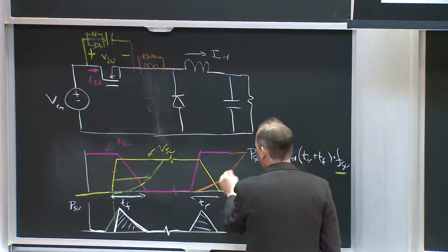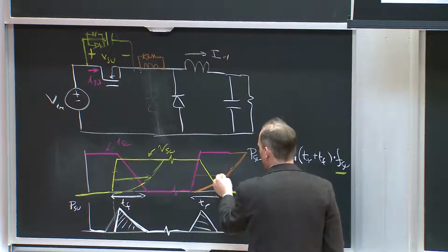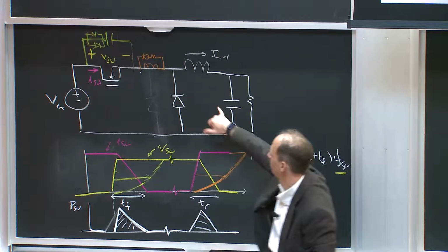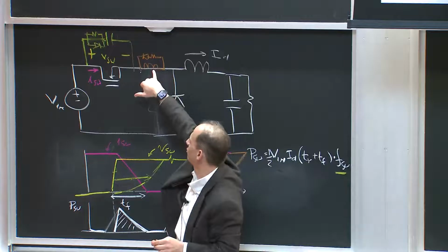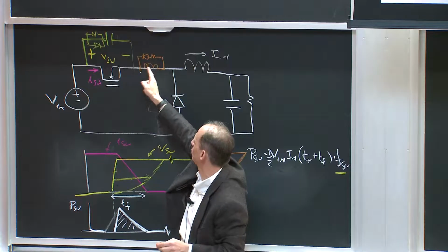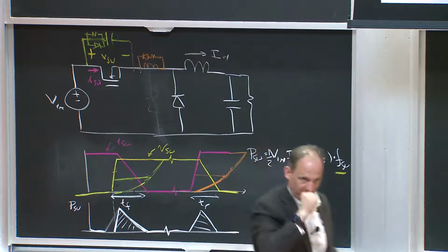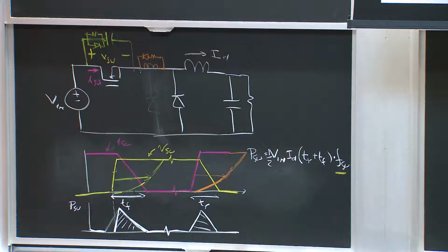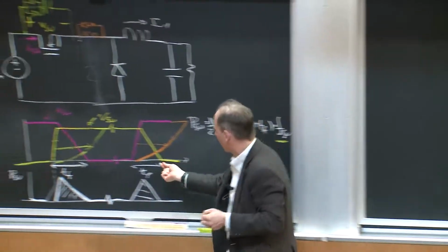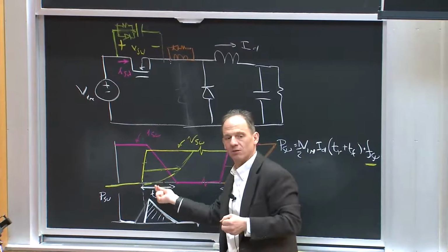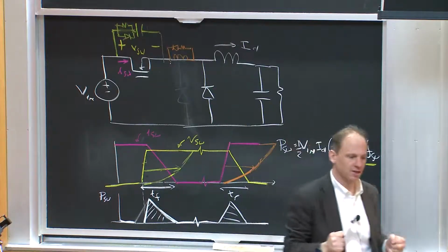And I will again reduce the overlap between the voltage and current by delaying the current rise. But I store a bunch of energy in this inductor. When I go to turn the switch off, that current will circulate in here and dissipate in the resistor. Okay, so again, I've reduced the overlap at the switching transition, but I've lost energy in the process on balance.